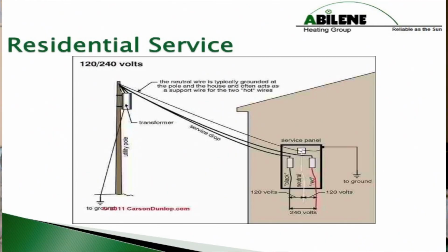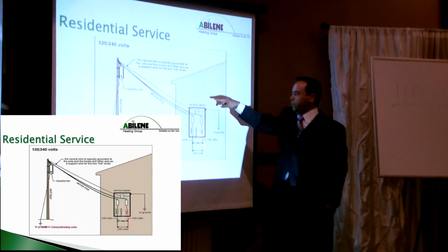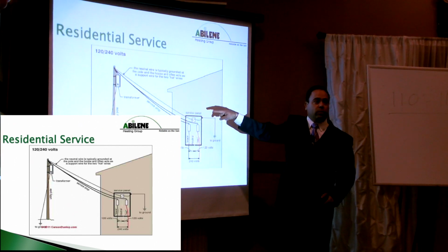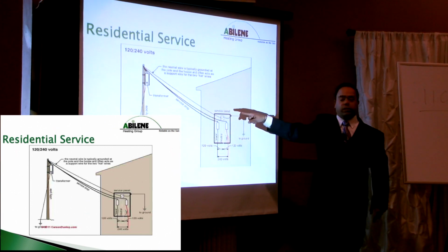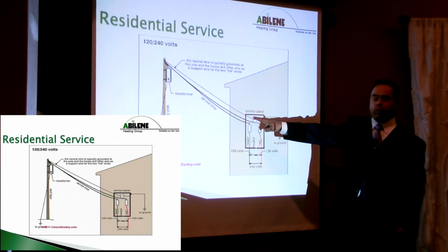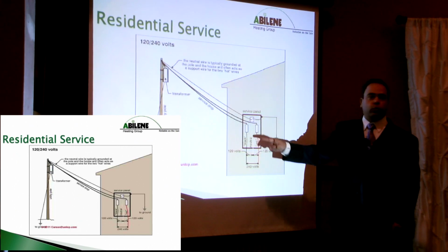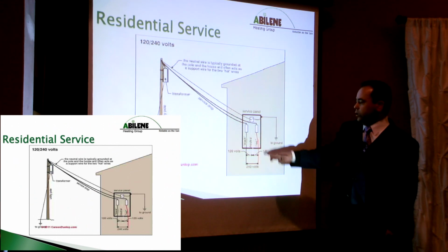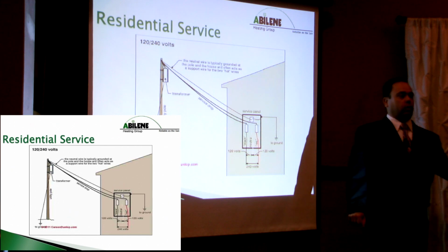This is what you guys see outside coming into the house. All right? So you have utility wiring at the pole. Comes in a loop to the house. Some of it's going to be underground. Some of it's going to be overhead. It's considered overhead service. And it feeds a panel, a service panel, into a main breaker. Feeds that panel. You have 2 hot legs coming in and a neutral. Between the 2 hot legs, you'll always get 220 volts, which is a generalized statement.